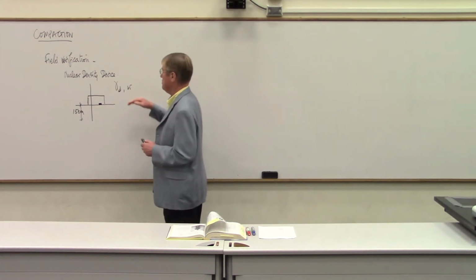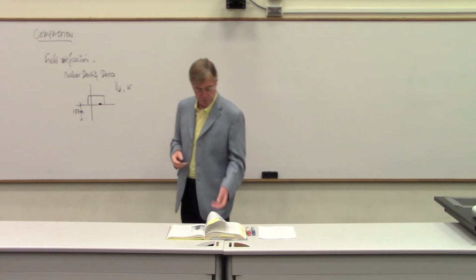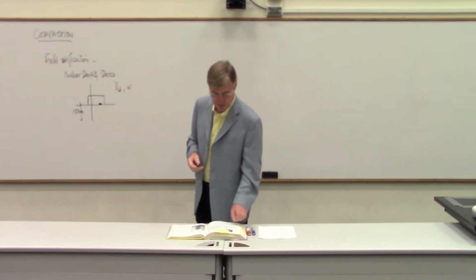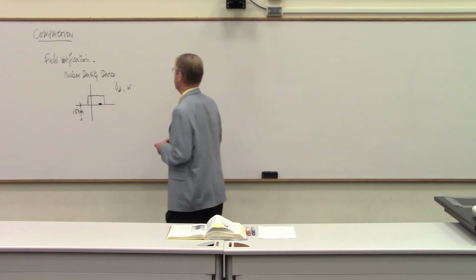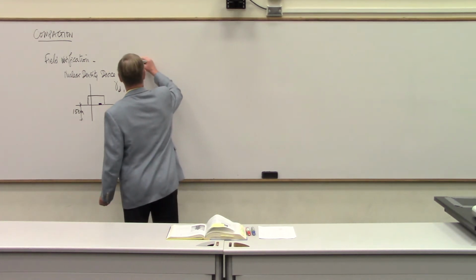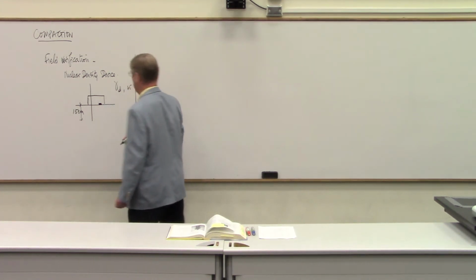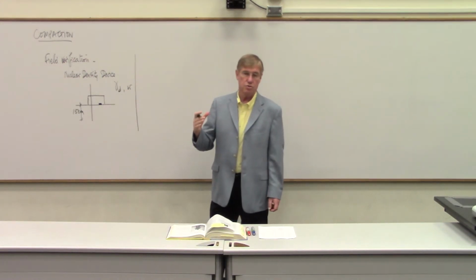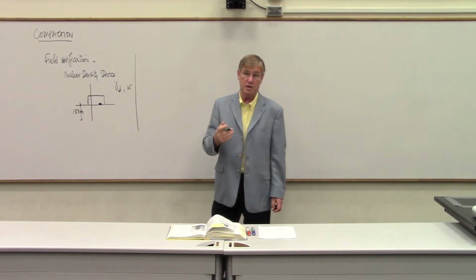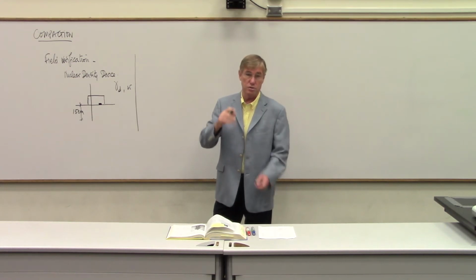The other thing that I wanted to mention before we leave the topic of compaction was that there is a trend today to go towards verification and compaction control based on the soil modulus, the soil stiffness.